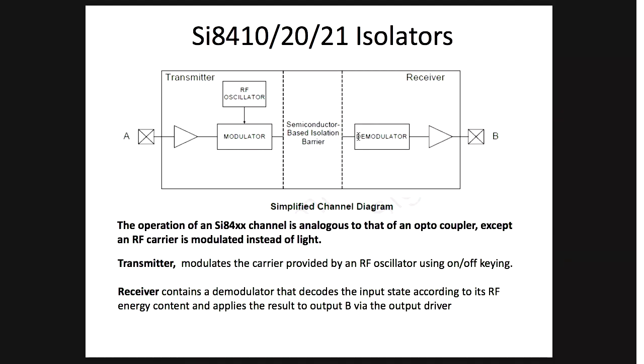So isolation is also an emerging area in research, because the problem is how will you isolate? DC isolation is okay, but when it comes to signal, depending upon the frequency, it is challenging. Like with the capacitor, you have parasitic inductance when the frequency increases. So with RF you can increase the data rate and at the same time get the isolation. Also, when you design RF, you should make sure that it is confined in that small region, because otherwise the RF will interfere with other circuits. So you need proper isolation when you are making these types of devices.